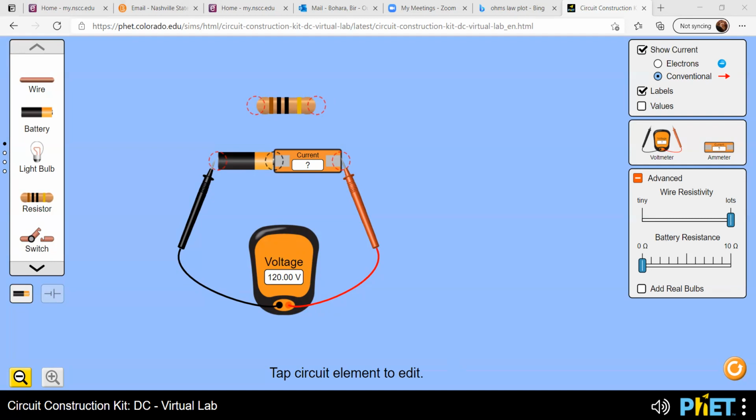I can measure the current through the circuit. The potential difference by using the voltmeter is there, right? And then I can calculate the resistance. So in this way, this device as a whole acts like an Ohm meter, right? And extra resistance. We will see what that extra resistance is.